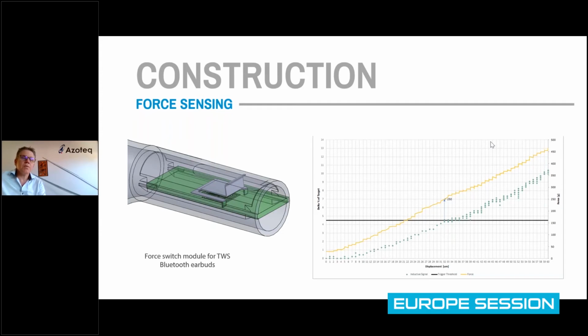In most instances, we don't open this temperature sensor to the users, but we rather use it for our internal algorithms to track changes in the baseline caused by temperature drift. So we also compensate on chip for any drift in baseline due to environmental changes. But the most popular one and the most controllable one is to use this reference channel. It is a very nice technique. You can even detect temperature shocks.